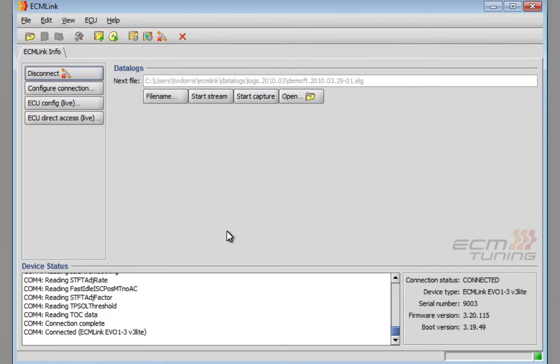The first thing you need to understand is there are two modes of operation in the ECU with regard to fueling. One is called open loop, the other is closed loop. In an open loop system, there is no feedback, so the system just assumes whatever it's doing is producing the desired result, and it doesn't bother checking up on itself.